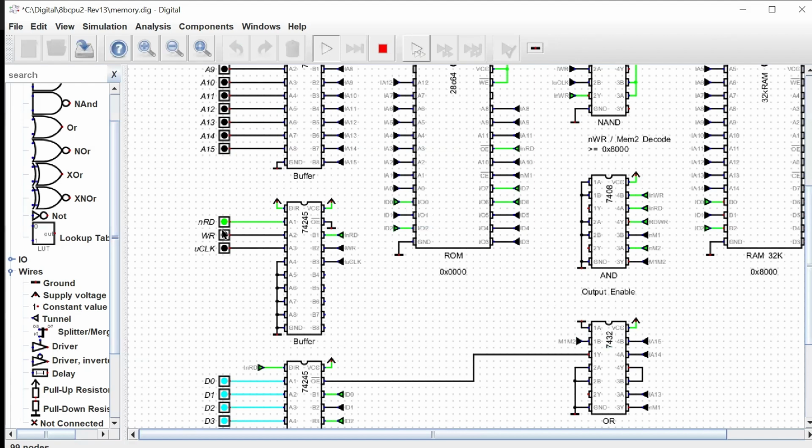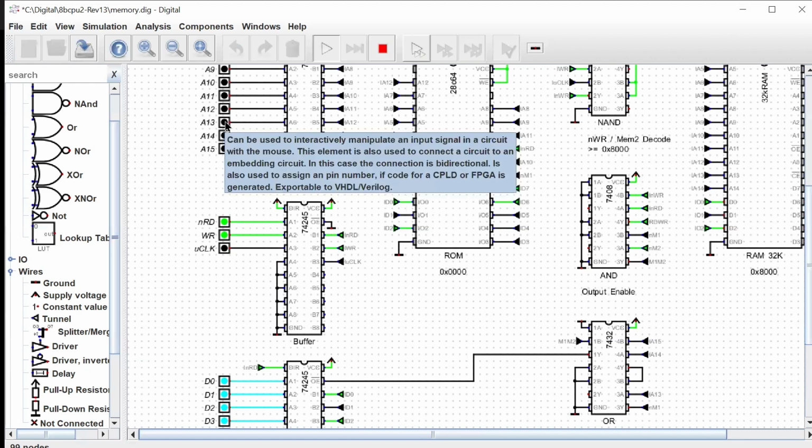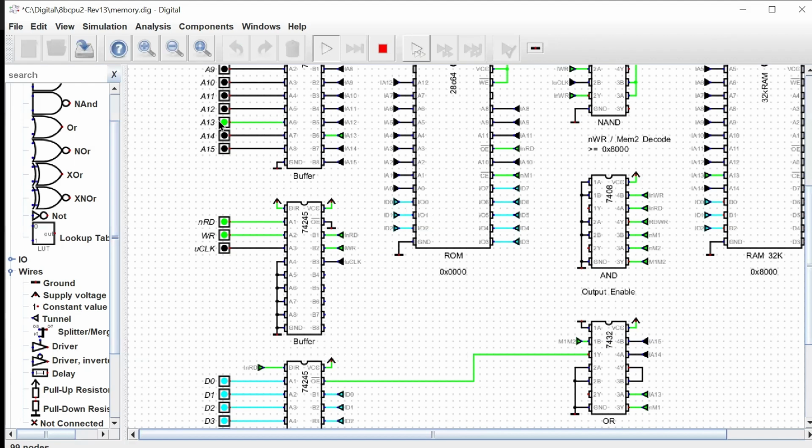So now let's take a look at the write signal. The write signal now is going to go high, but again, this signal is already active low because the address is in the range of our ROM and our RAM. Again, if it's not in the range of our ROM and RAM, hex 2000, the output enable is high, and our data bus driver is in a high Z state again. So that is effectively our fix.